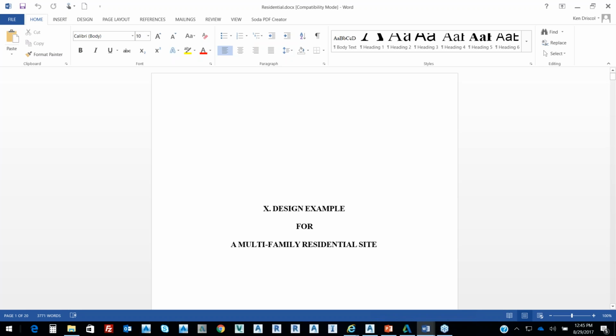Storm Sanitary Analysis is very schematic in terms of what it brings to the table. What do I mean by schematic? That means I don't have to have a 90 or 100 acre site actually in the program. It reads from runoff coefficients and friction numbers for the analysis. So we just want to keep that in mind.